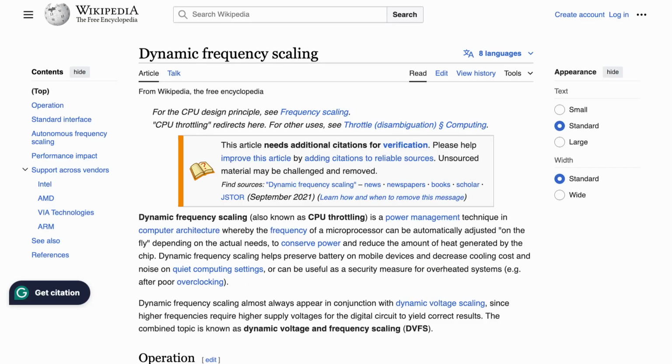Then the engineers put some countermeasure in place and it automatically cuts off power when it reaches a certain temperature threshold. Think of it like a thermostat in your oven. Practically, it is the same principle as a thermostat in an oven. So if it's too hot, then it just cuts power entirely. That is step one. Step 2 is introducing something called dynamic frequency scaling, or DFS for short, and it